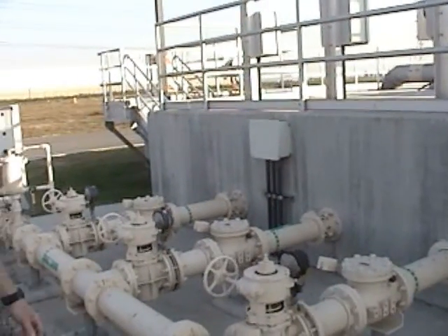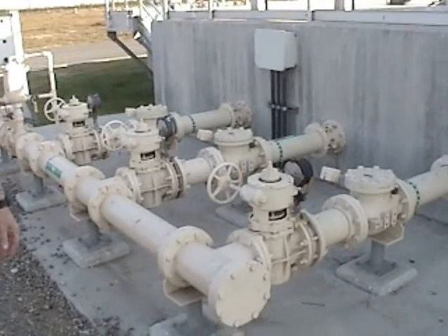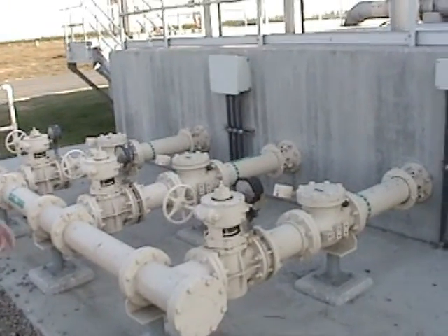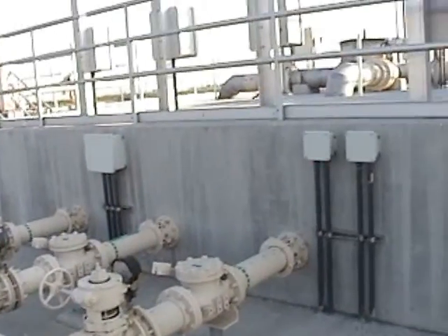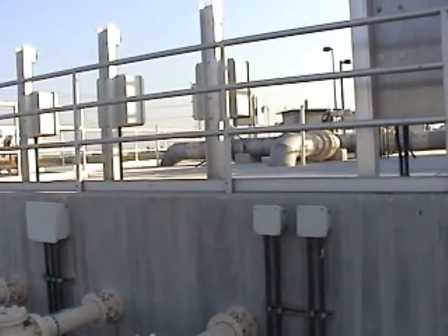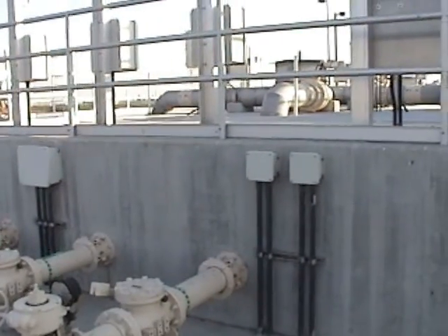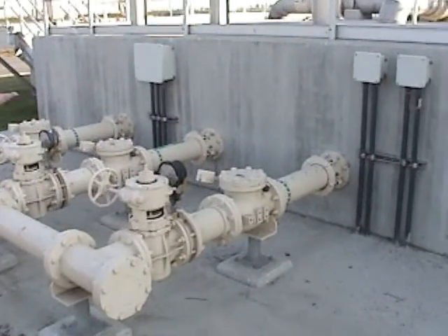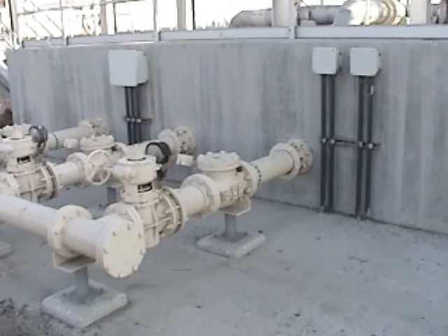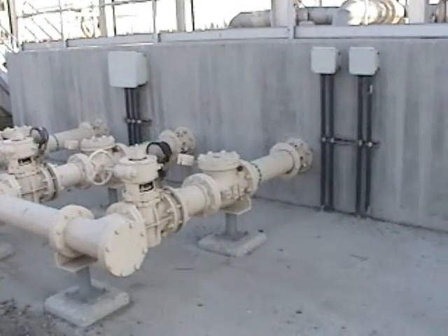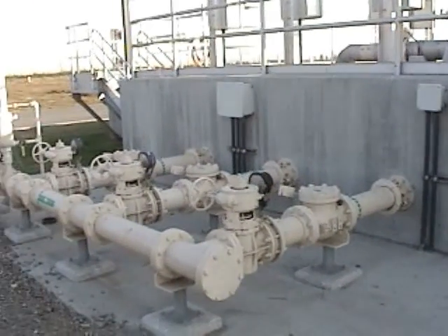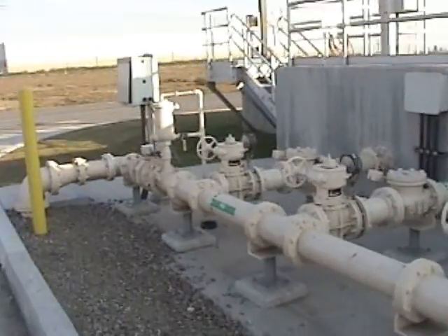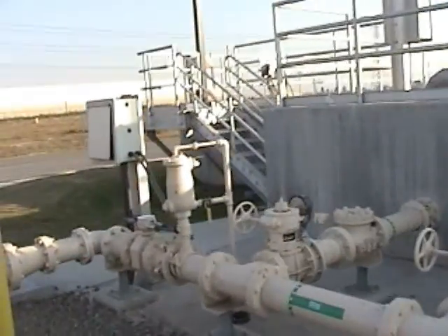And the problem that we've had here is the backwash water contains a little bit of sand in it from the filters, and at times the sand will pile up around the intake of these pumps, and you'll have to pull one out, and you may find that there's a lot of sand caught up in the impeller. There's 3 of them. Usually we're running 2 of them, which should do the job.